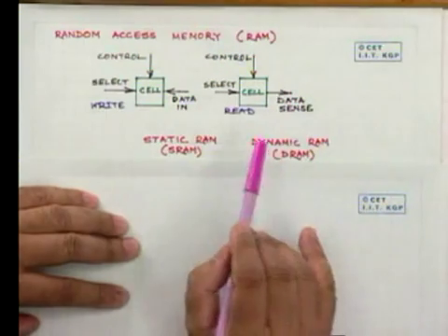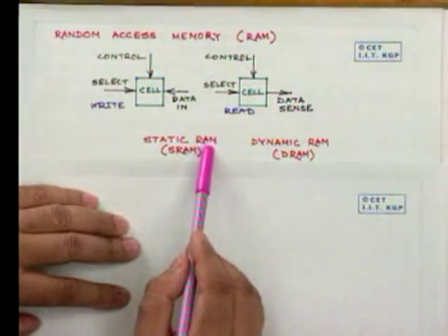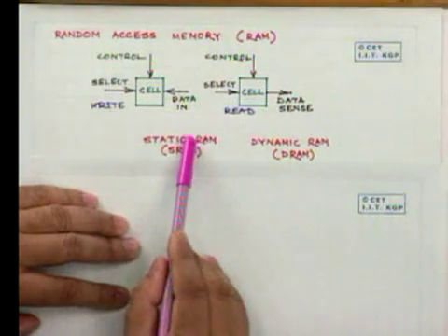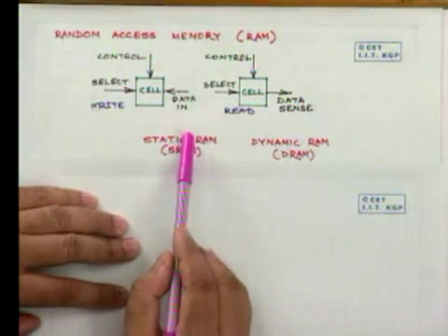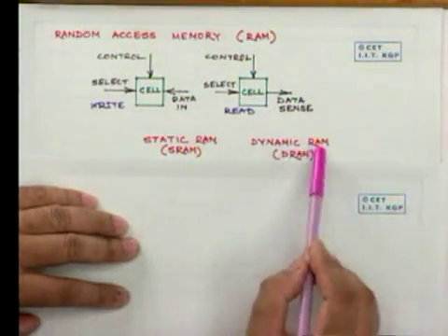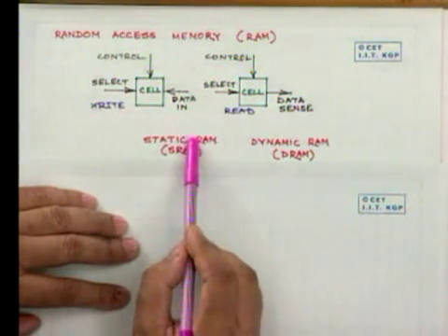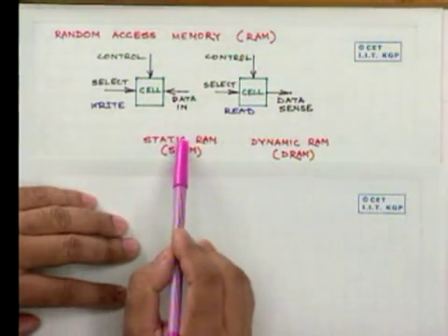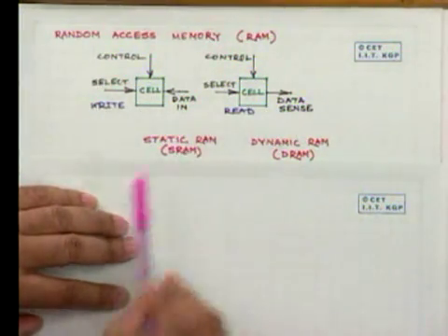The reason I am telling this is that in the case of a static RAM, it is an interconnection of several active devices, making it a flip-flop, so to say. And in the case of static RAM, that flip-flop holds either 5 volt or 0 volt, depending upon whether it is 1 or 0. I mean, when I say 5 volt, it is near 5 volt. When I say 0 volt, it is near 0 volt.